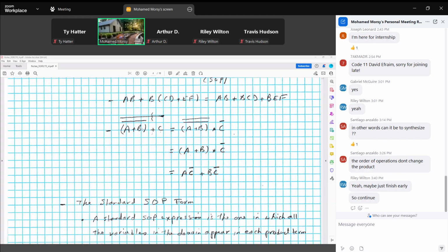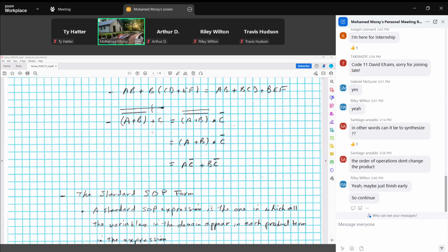Again, this one here. This definitely is not sum of products. So how do we convert it? Immediately when we see this expression, this means we can use De Morgan's theorem. For the big bar here, the upper bar, we can cut it into two bars. One part goes to A plus B, so A plus B double inverted, and C inverted.